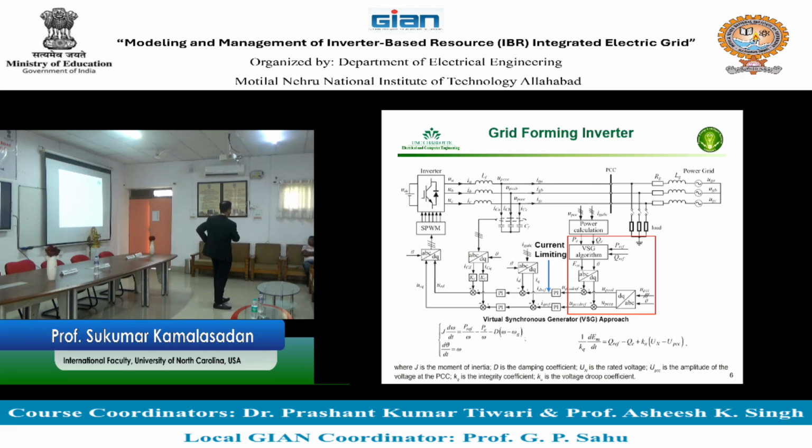Is a governor there in this model? No governor. Can you include the governor here? Yes, you can. That equation right here, you can actually extend it to provide the governor equation. If you provide the governor equation, you will get one more derivative. We add the derivative here. So one derivative for the swing equation, one derivative for the governor. If these two derivatives are included, then your governor equation is also included. All equations, by the way, there is no real generator. So the governor equation you can add.